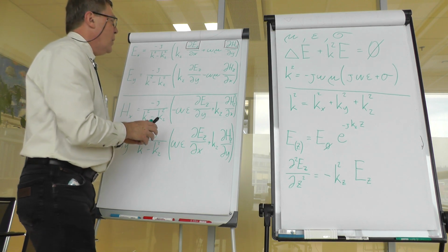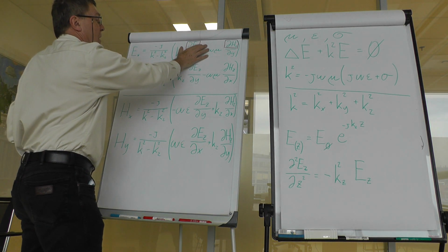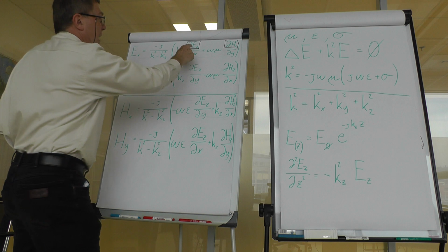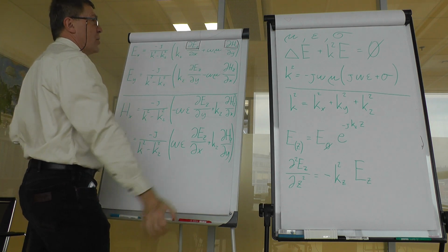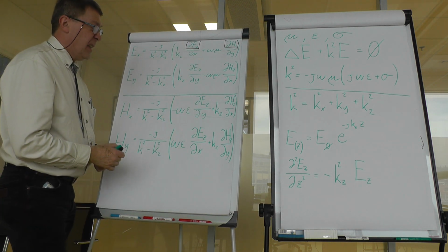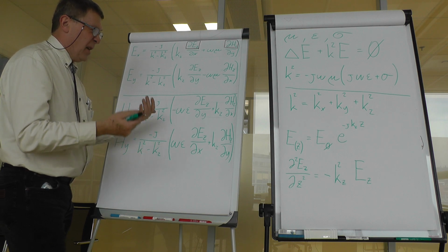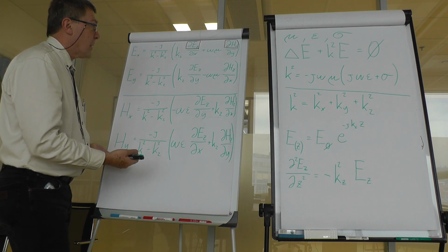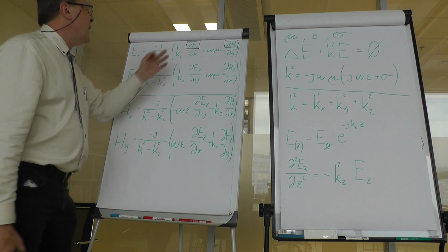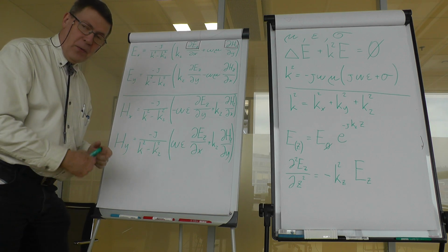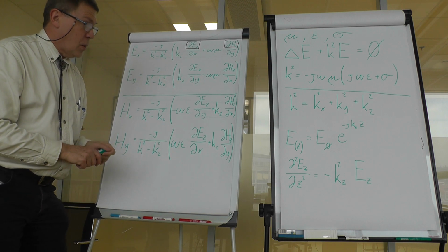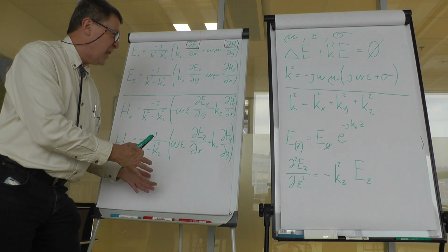So those are 2 independent fields that you can handle as created by the component of the electric field strength in the z direction, one half of the field, and the magnetic field intensity in the z direction, like the second part of the field. And yes, in waveguide theory, which some of you have studied already, the Ez field generates something which is called transverse magnetic waves, and the Hz generates something which is called transverse electric waves within a waveguide.